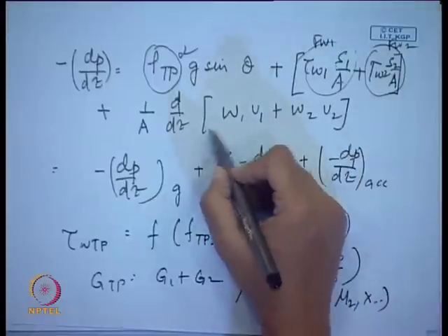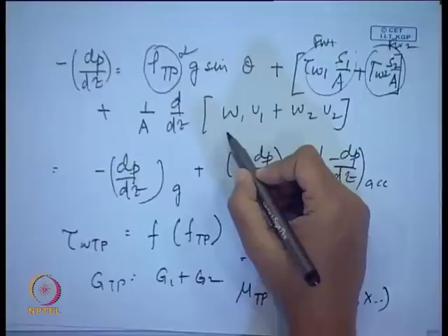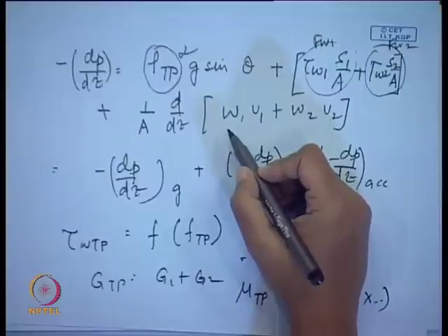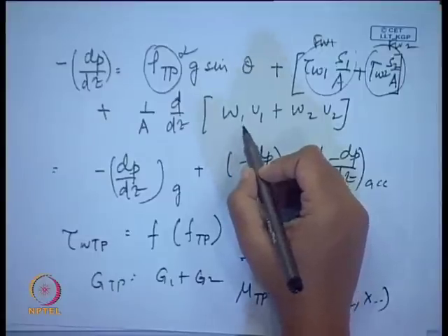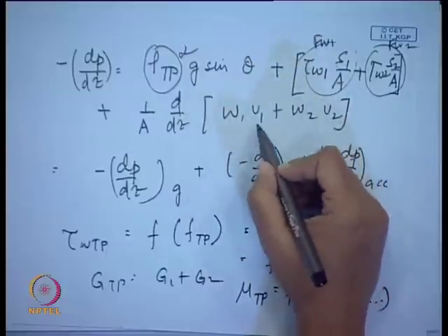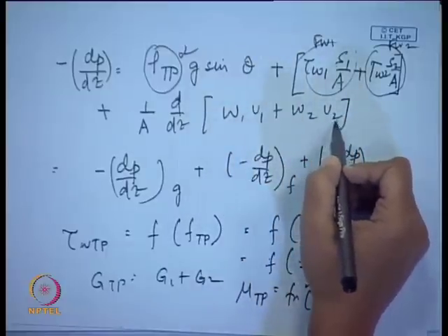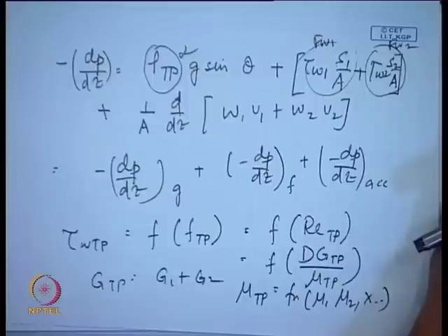For that, we will be dealing with the acceleration pressure gradient just as we had done for the homogeneous flow theory. Now, whenever we try to expand this U1, U2, normally we get some terms containing dP/dz, isn't it? Why? Because V1, V2 etc. vary with pressure. So, when they are brought on the left hand side, we find that the final pressure drop equation has a denominator. From there we go on to derive the condition of choking. Is it clear to all of you?